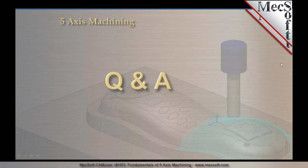But even if the secondary solution is not reachable, then what we do is we actually error out. We will mark that as an error toolpath, and you will be able to see that in the toolpath editor as an error position. And obviously, you'll have to go back in and try to reprogram that part so that your machine can actually handle machining that type of geometry that you're programming. I hope that helps answer that question.